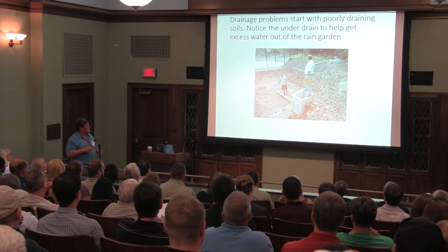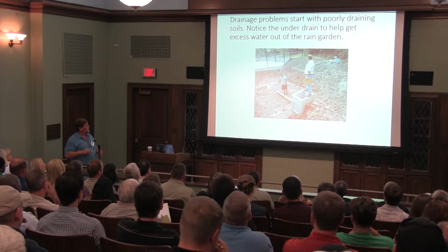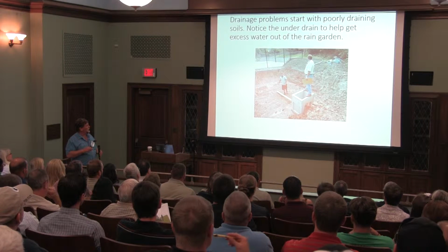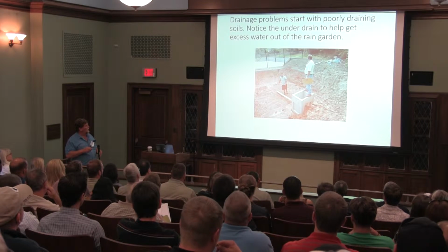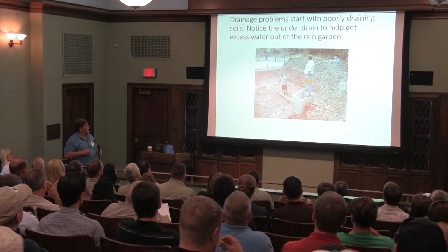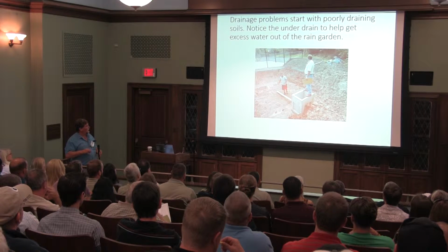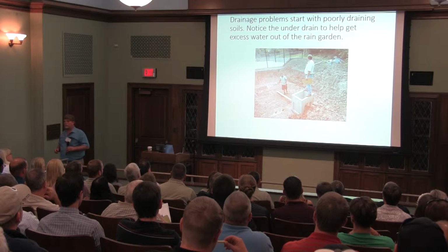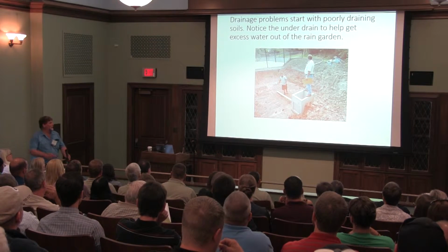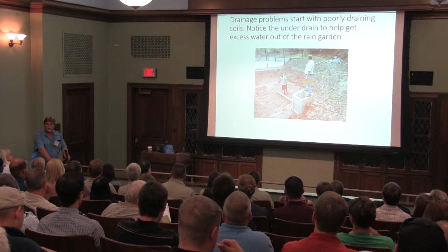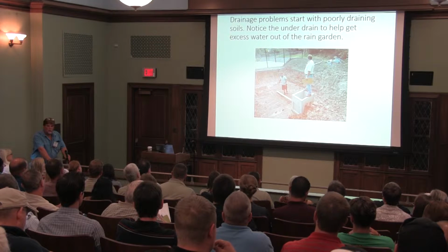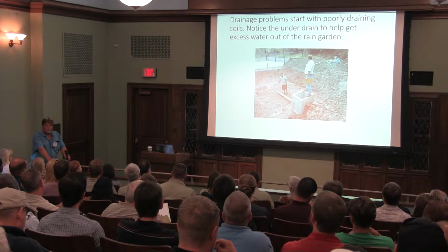so this is a rain garden. We had to build this to control the water off of that basketball court in a fellow's backyard. And right away, you can see we're in red clay. Not going to naturally take the water itself. It will, but it's slow. Clay does absorb water, but it is slow.